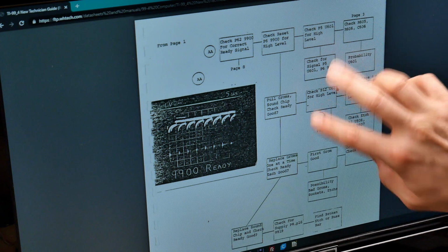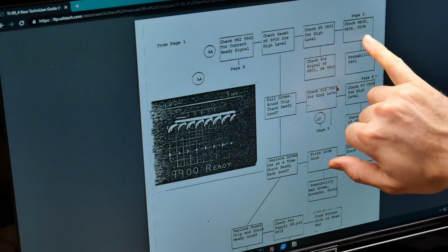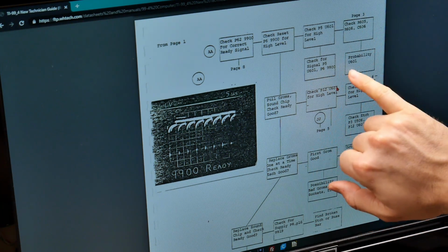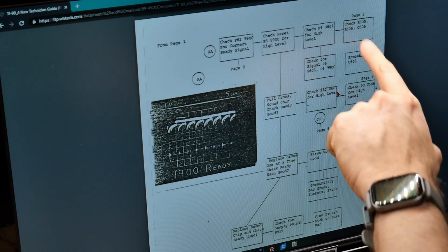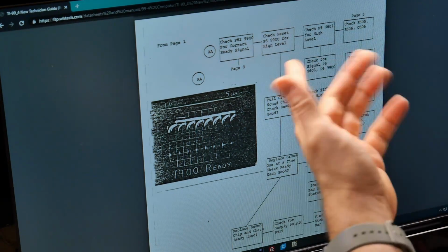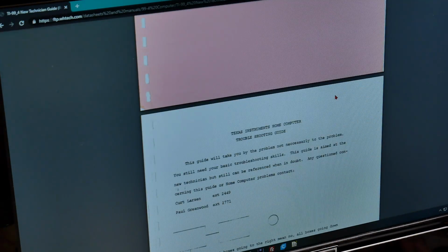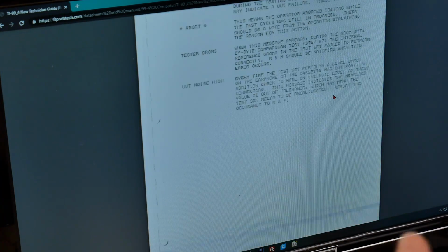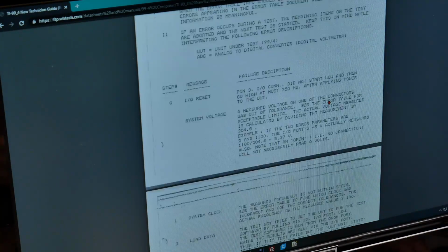And this only has like a couple outcomes, right? It wants you to check a signal here, and it wants you to check some other stuff here. And then it says U601 is the probability. So let's look at what U601 is and these other things here, right? I mean, I don't know. I think I'm going down a dead end with this, and the troubleshooting I did earlier showing that the data lines are screwed up is actually more an indicator of a problem.